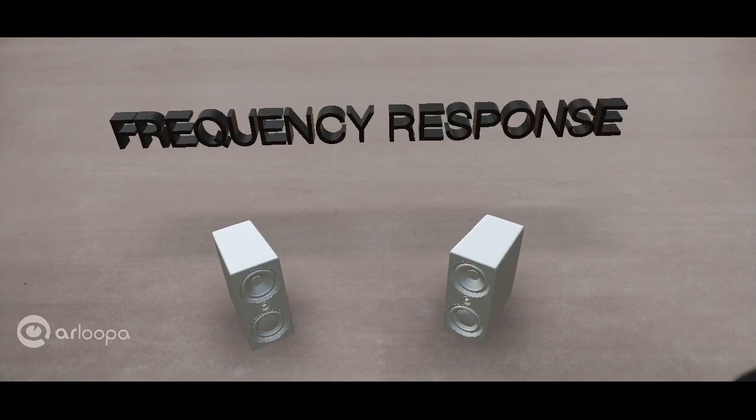Now, estimating the frequency response for a physical system generally involves exciting the system with an input signal, then measuring both the input and output, and then calculating the frequency response. It is very important to note that the frequency content of the input signal must cover the frequency range of interest of the physical system.